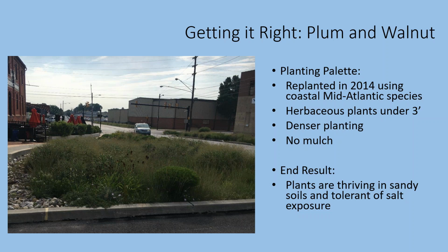In 2014, we worked with a woman named Claudia West, who wrote a fantastic book called Planting in a Post-Wild World. And we took a look at the soil profiles that were specified for this particular installation, looked at the sand content, and developed a palette that included more coastal mid-Atlantic species. So not necessarily Pennsylvania native, but very regionally native. We also wanted to make sure that they were herbaceous plants that typically grow less than about 36 inches to maintain site clearance, because you did see some of those porous paver areas.